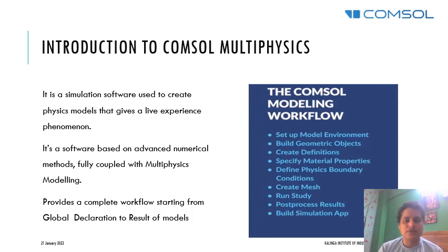In case of PCF, we need to define the radius, diameter of the air holes. We need to define the pitch between the air holes. Then we need to define the operating wavelength, and all sort of optical parameters need to be defined in the global declarations. And in the component sections, we need to build the geometrical objects. Either it may be a circle.